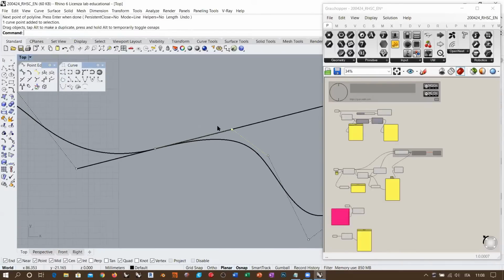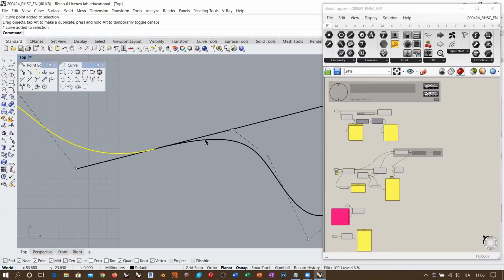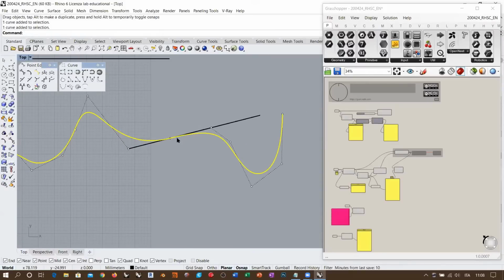So basically what I'm saying is that the end tangent of the first line is coincident with the start tangent of the second line. It means that the two curves have the same direction in the connection point, which is the second definition of continuity in one point. So you see that this first rule, which defines the initial and final tangent for a curve, is already useful to create a visible continuity between two different parts.